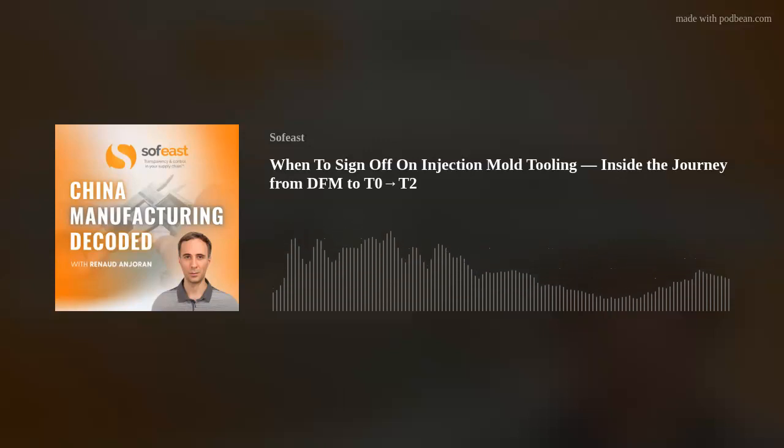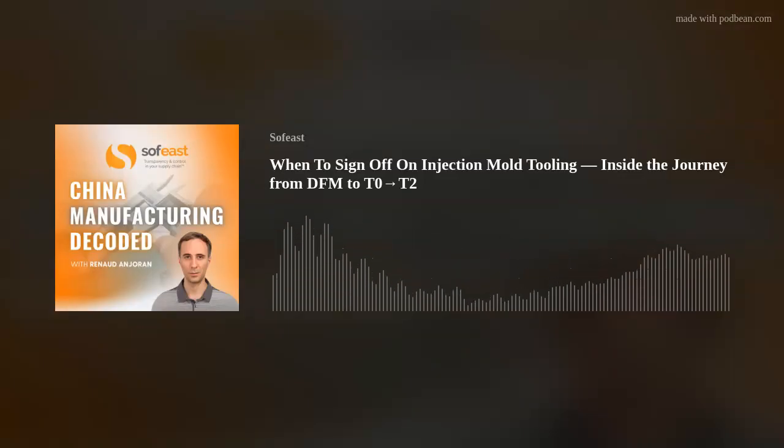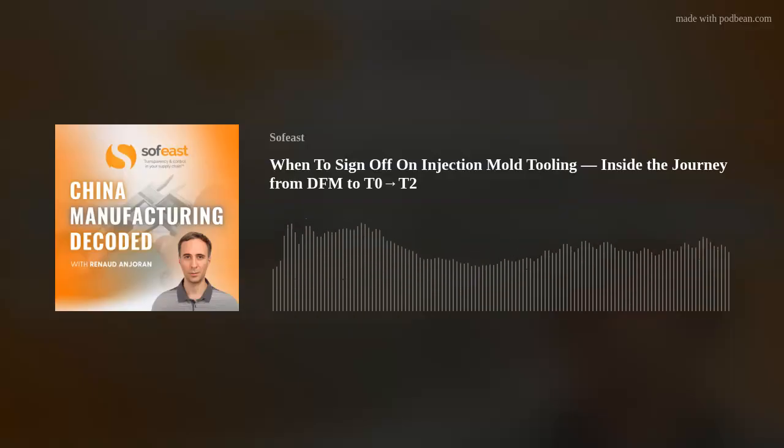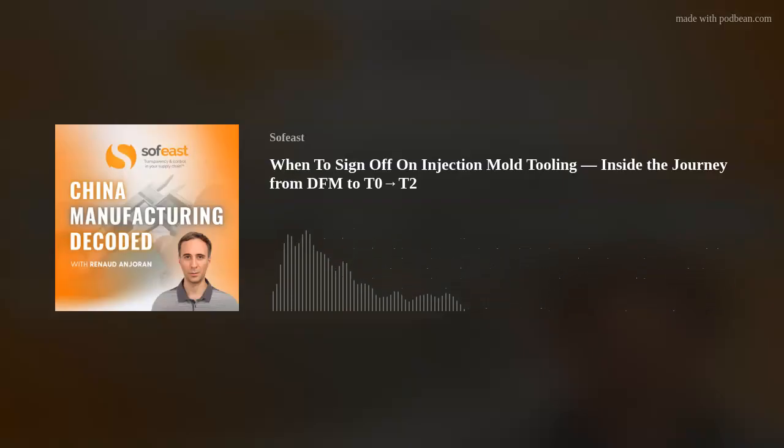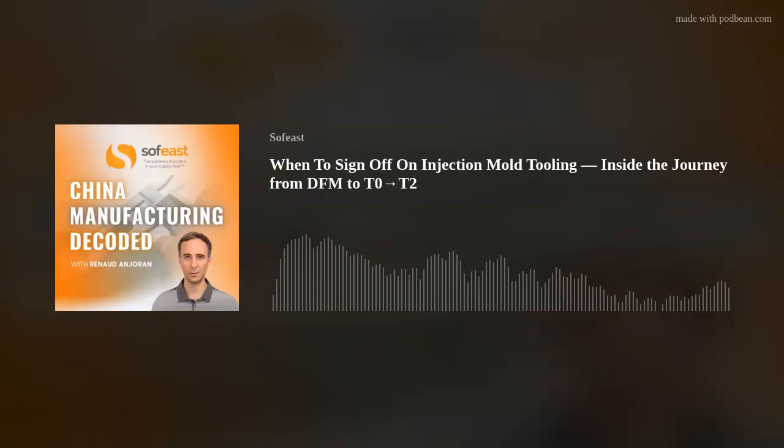We generally start off on CNC, roughing out. We've got a couple of 5-axis CNC machines in our plant. This is where we're roughing out the shape of the core and the cavity. From there, we will also be machining brass inserts for the EDM machine. EDM is electro discharge machining, commonly known as the sparky erosion.